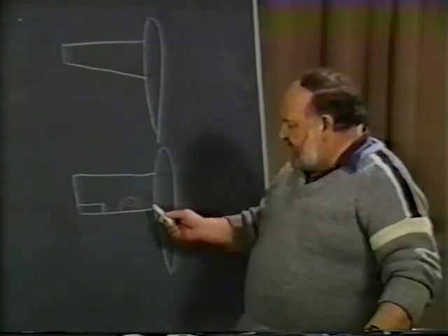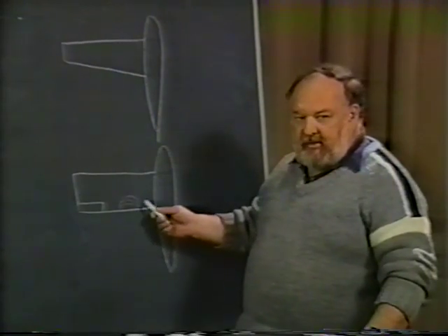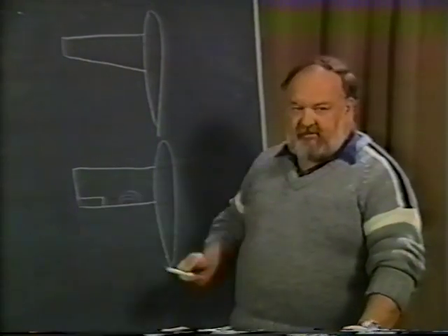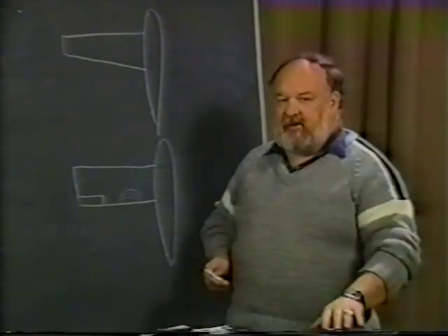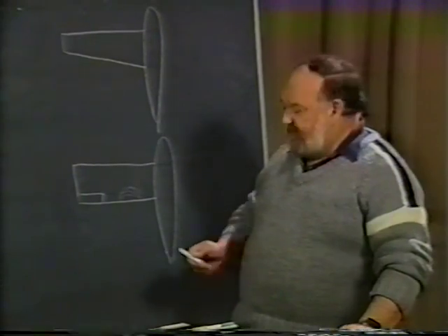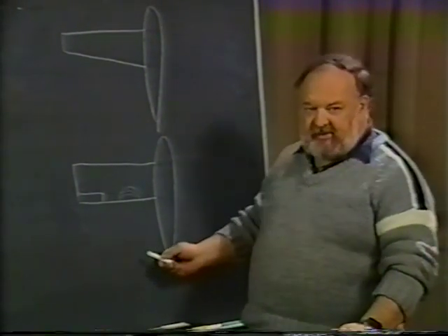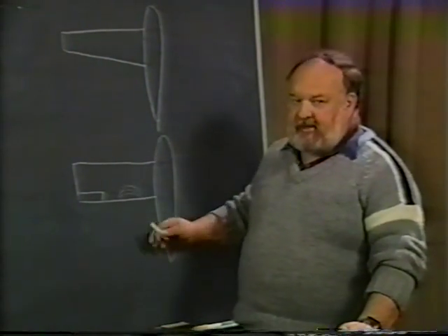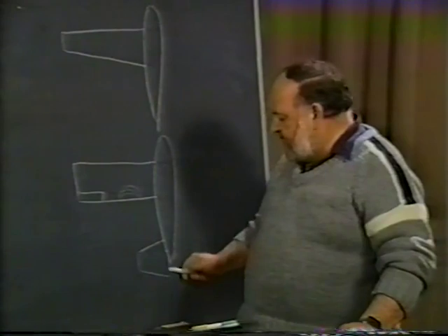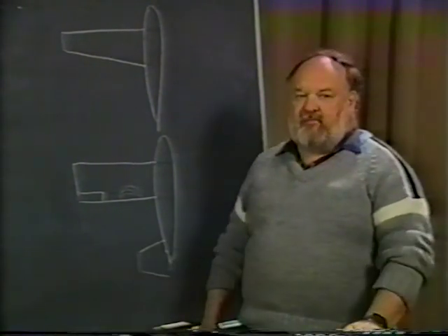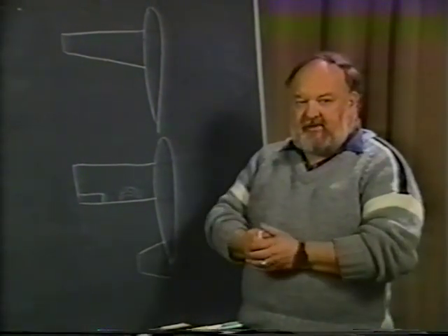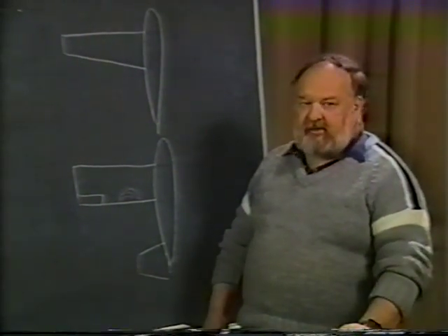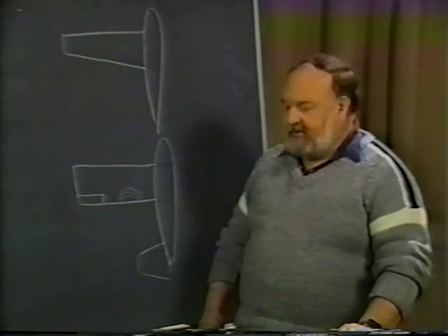If it begins at the root section in here, or inboard anyways, you will now get a nice type of buffeting. The outboard section will still fly. The airplane itself will start to pitch over a little bit, but not very violently. A little side effect to it too, if you have a standard tail configuration in the back, by getting flow separation beginning inboard like that, this turbulent air will then start to impinge upon the horizontal tail, and the pilot himself will actually get more stall warning, because he'll feel it within the stick, because the horizontal tail will sit there and start vibrating and shaking a little. This is a real good stall warning system. Without a question about it, that's a good way to do it.